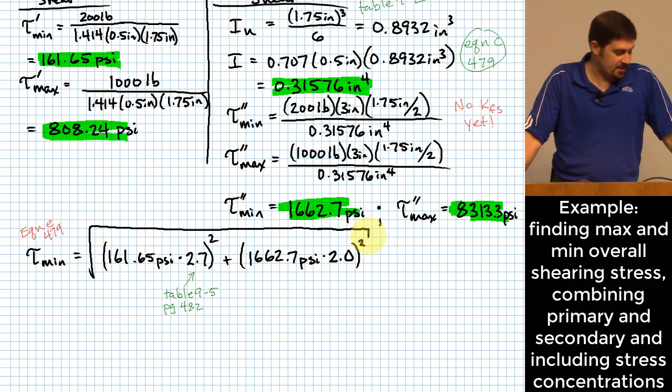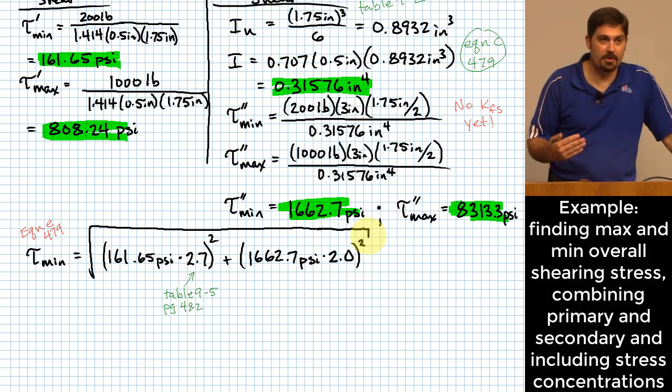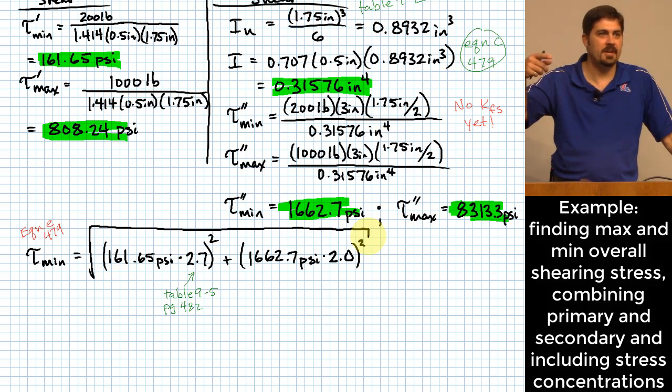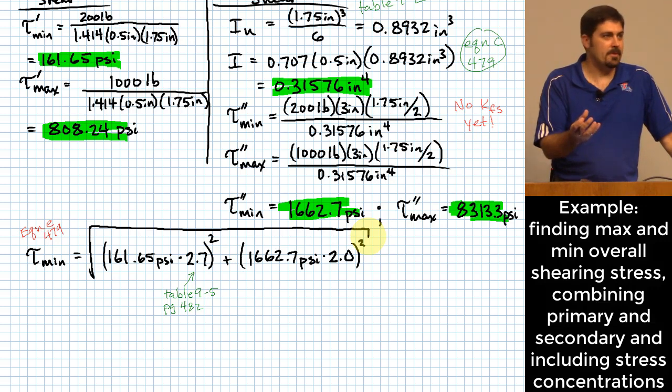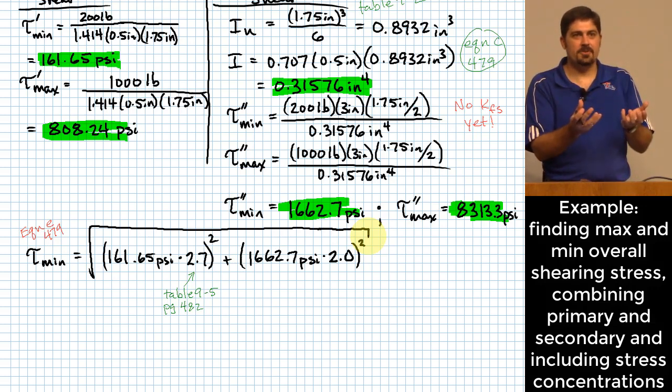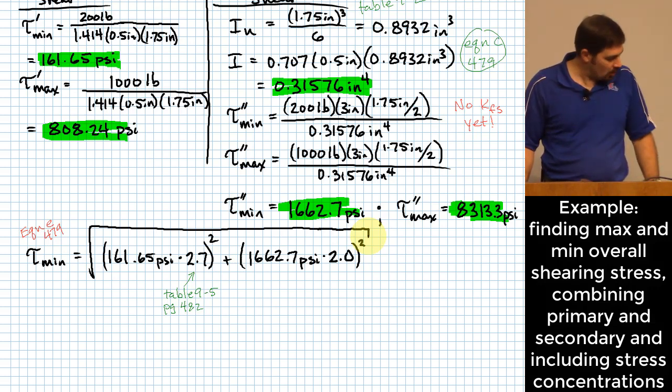For that reason, a lot of times some folks, as soon as they see there could be a stress concentration factor, just use 3. I've seen people do that before where they say, oh, that looks like there's going to be a stress concentration factor right there, don't want to get into it, let's just assume it's 3. All right? I'm not saying you should do that. I'm just saying that's one of the ways someone could go. If you want to be a little less haphazard about it, you can do what I just did and come up with the closest situation to what I think is causing the stress and why there's a stress concentration. More generally, there might be other situations that aren't stress concentrations where you still have to ask what is physically most the same as the information I have to work with, and then do your best to estimate based on that. Anyway, hopefully that helps a little bit.